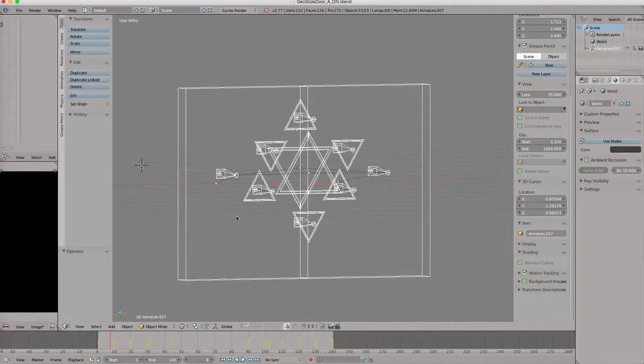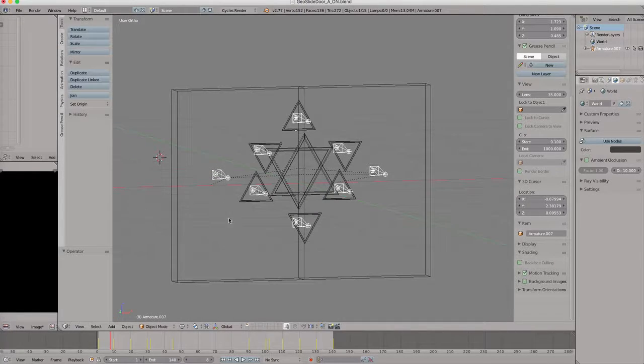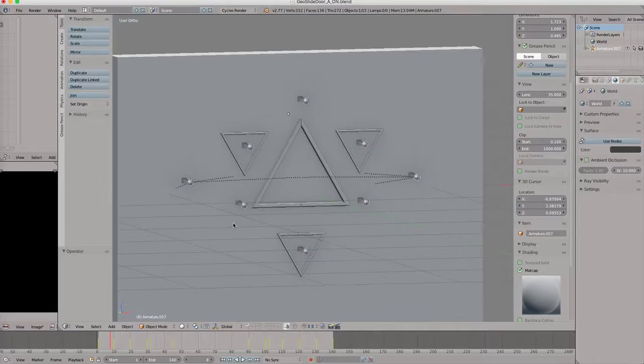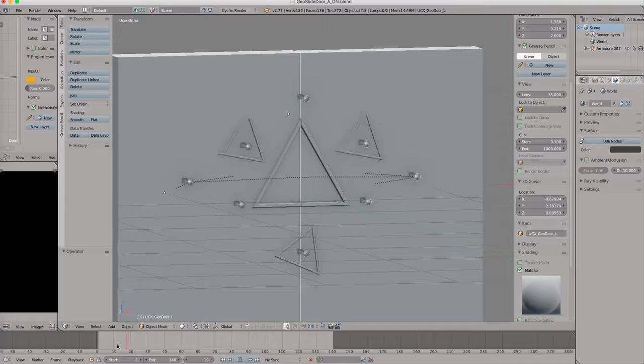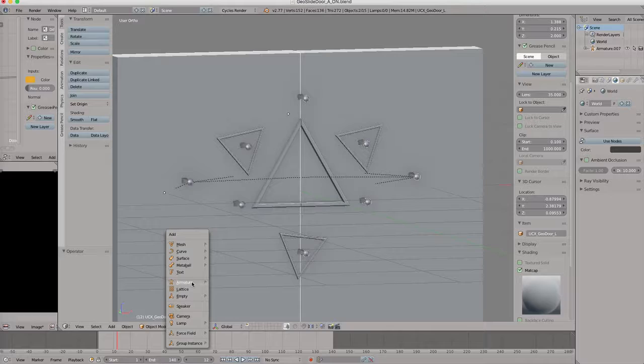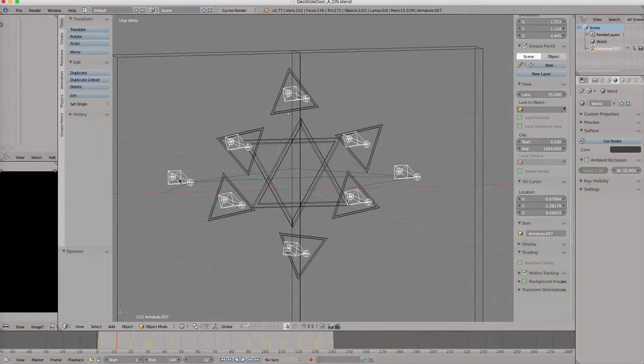So in Blender, the bone system, they all had to be parented so that they work correctly in Unreal. So don't go Shift A, create an armature, a single bone, then Shift A and create a single bone for each one of these. You can just, in the end, make sure that you connect them all.